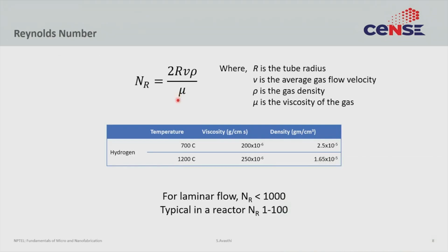In order to maintain laminar flow, the Reynolds number must be below 2000, which leads to the question: what is the Reynolds number? I will not quiz you on this, but just for your information, the Reynolds number is simply a unitless quantity, which is given here, which basically tells you how fast the fluid is flowing through your tube. And if it is flowing too fast, then the flow becomes turbulent, which is bad.